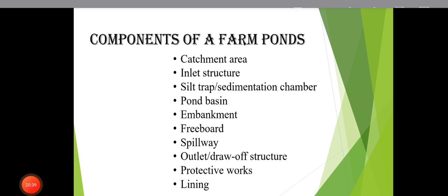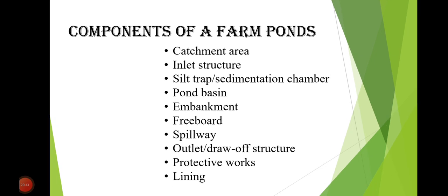So the next is silt trap, or sedimentation chamber, basin or anything else. A silt trap is constructed at the inlet side. The functions are to prevent sedimentation from entering the pond, and increase the effective life and storage capacity of the pond.